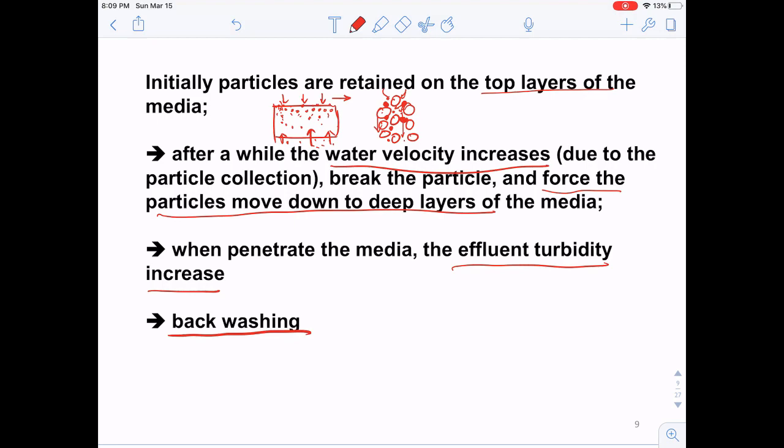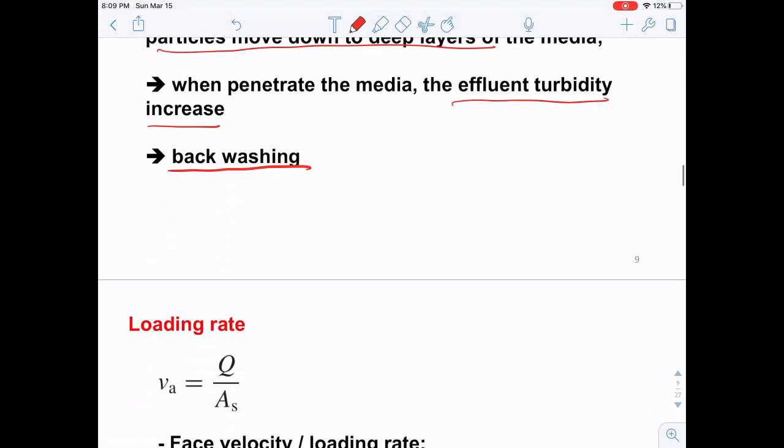But by cleaning these filters, we have to stop the upstream flow here, right? And then push the contaminated water back out of the filter there. So for these filter setups, we always construct multiples of them so that we can easily take them offline when we're trying to clean up these filters, okay?